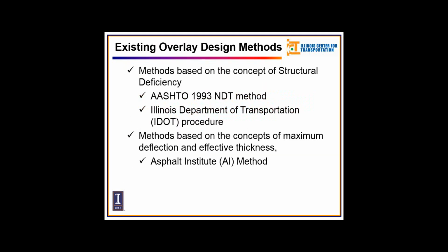In order to do so, we took a look at the existing overlay design methods, and we found that there are two methods. One is based on the concept of structural deficiency, which is followed by the AASHTO 1993 NDT method and also the IDOT procedure. And another one is based on the concept of maximum deflection and effective thickness, which is followed by the Asphalt Institute method.